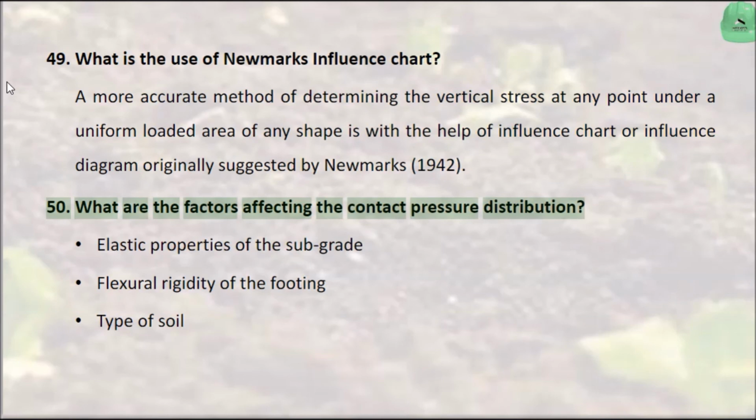What are the factors affecting the contact pressure distribution? Elastic properties of the subgrade. Flexural rigidity of the footing. Type of soil.